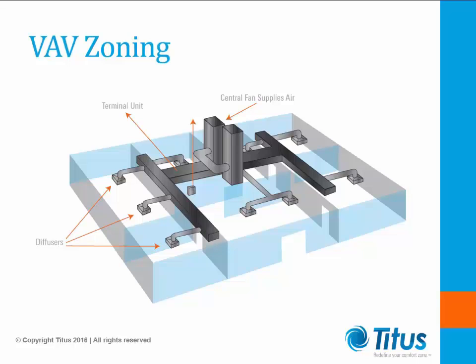One of the easy ways to zone a building is the use of thermostats. You use the terminal units to deliver air to a particular space in the building, but thermostats give you that control that helps localize the comfort of the occupants. VAV boxes efficiently distribute airflow, and the airflow is determined by how much air is needed to satisfy the room temperature.